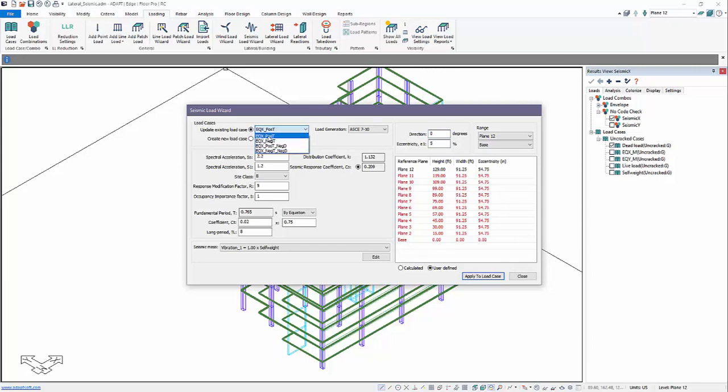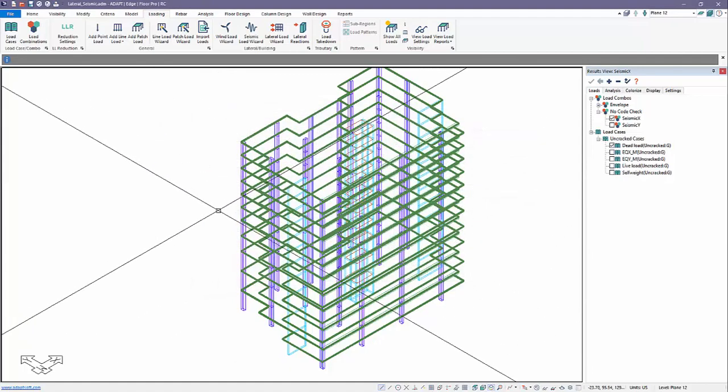sets of load cases for seismic. The program uses these cases to generate story forces. Those are only calculated once we actually solve the system. The program distributes the story force at a nodal level, nodal forces, nodal moments based on the torsion, and those are all tabulated and solved for at the onset of analysis. We'll go ahead and close this.